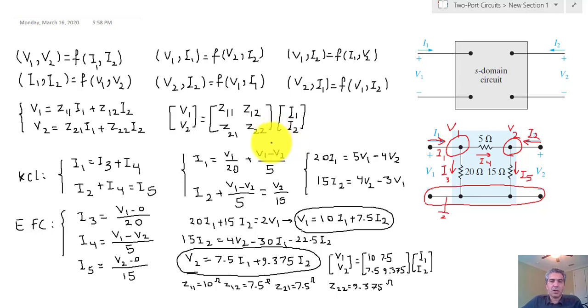And the beauty of it is that once you have this set of equations, you can actually derive any other of these 5 other equations that you want. So like I said, it's just a matter of manipulating these equations. Now, the same set of equations, I can actually write them as a function, write I1 and I2 as a function of the voltages, which is exactly what we have here. I don't have to really do anything for that. And then I have this definition. And at that point, the matrix is called something else.